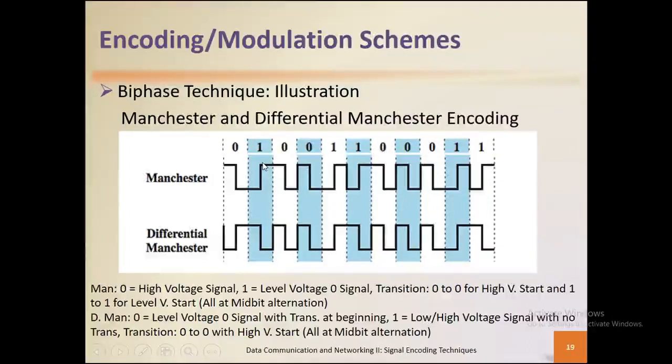Okay. So just keep this in mind. Don't be confused or anything. Zeros start from a high voltage pulse, and all bit sequences must transition mid-bit. Just keep that in mind with the biphase. It must transition mid-bit. So with that in mind, and knowing that 0 has to start from a high and 1 has to start from a low, you should be able to figure out how to manipulate the signal graphing to address some of these highs and lows and the transitions within mid-bits.